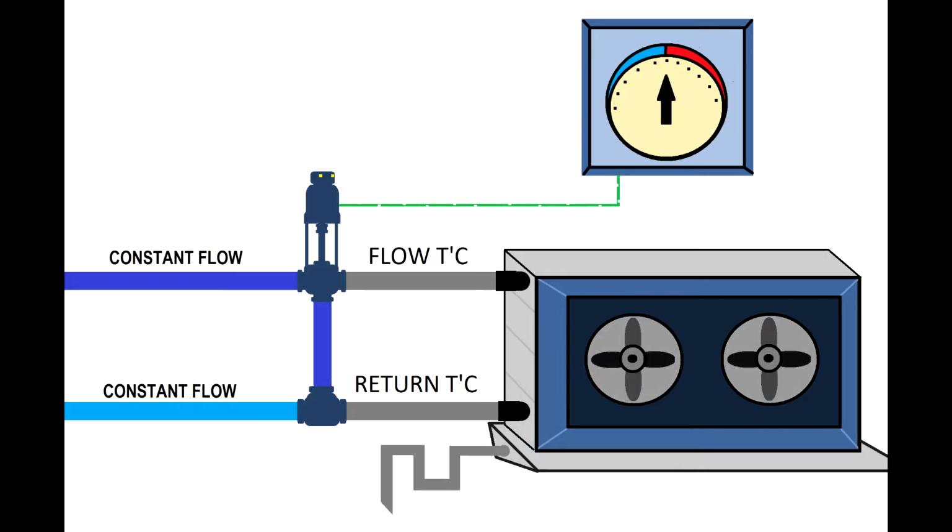Just like the heating, in the cooling fan coil unit we use a heat exchanger that allows a cooling agent this time to pass by. So we will cool the premises, the fans will circulate the air through the very cold heat exchanger, and then the premises will be cool. Unlike the heating, you will see underneath this heat exchanger we have a drip tray with a drain pipe.